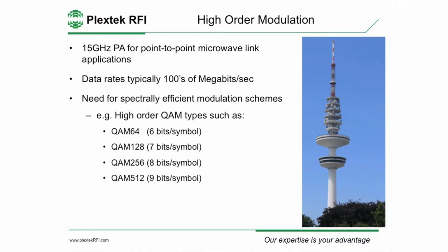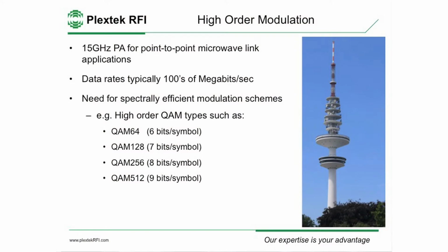So all your teenagers down in the latest tweets or the gaming apps, all of this is to cater for them. And there's tons of stuff to backhaul. All your iPhones continuously polling the network for your mapping features, all generating tons of traffic to backhaul. And that is why the amount of data we need to backhaul is going up, and we're being pushed up the modulation schemes. QAM 256 now, it's pretty standard to operate with 256. 8 bits per symbol. 512 is being rolled out, as is 1024. And in honesty, there looks like there's no end in sight.